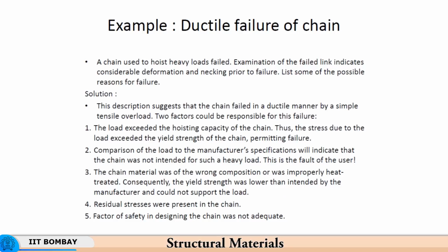But then what has happened is you have welded it, and once the weld has cooled down, this chain will try to release its elastic stresses. So, these two ends will tend to move apart, but that is not being allowed. Why is it not being allowed? Because the weld is holding it together. But the tendency of these two ends to go apart will result in continuous tension being introduced into the weld which you have made. So, that is what we call residual stresses.